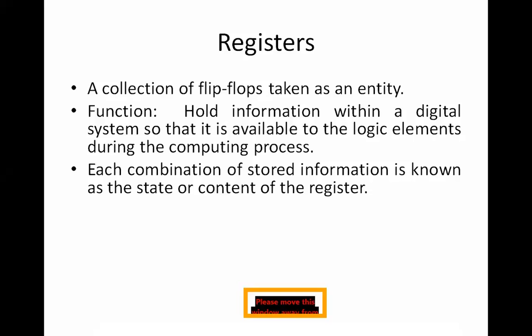So we are coming up with a new thing called a state. Remember the block diagram that we saw, right? One had state, in the initial part of sequential circuits. We discussed a block diagram, right? One of the outputs was called state, right? We will go deep into that. Each combination of stored information is known as state or content of the register. So whatever data is inside the register is called a state.